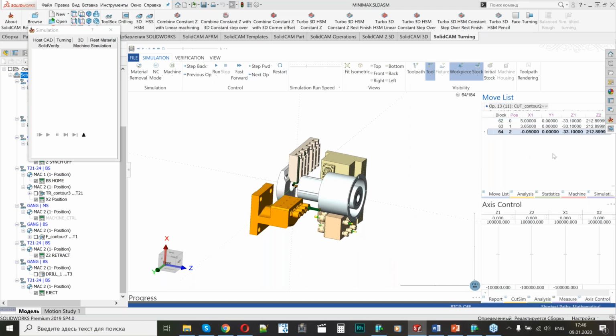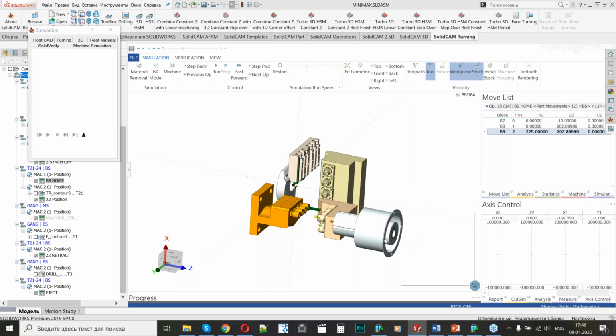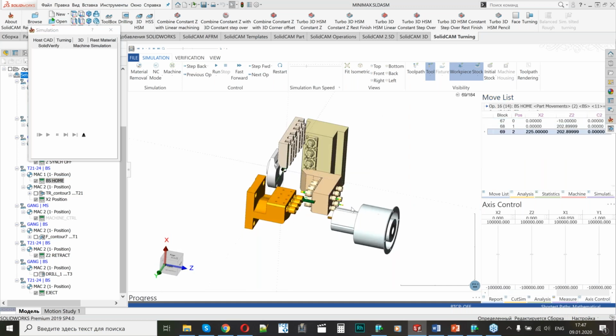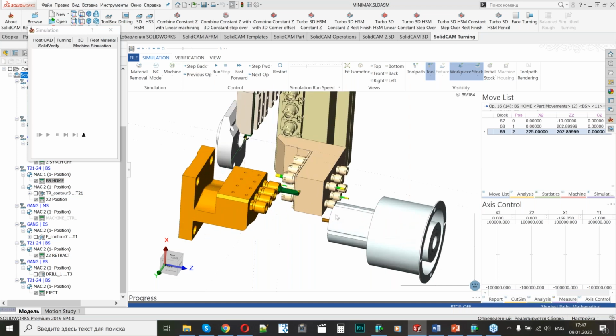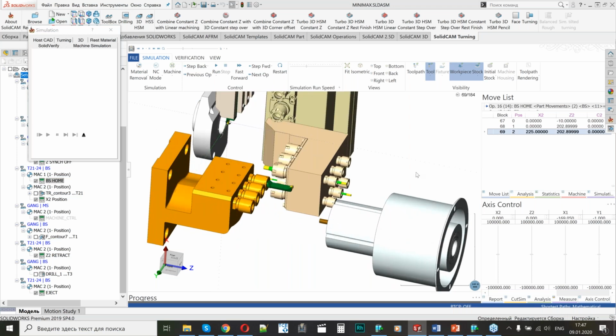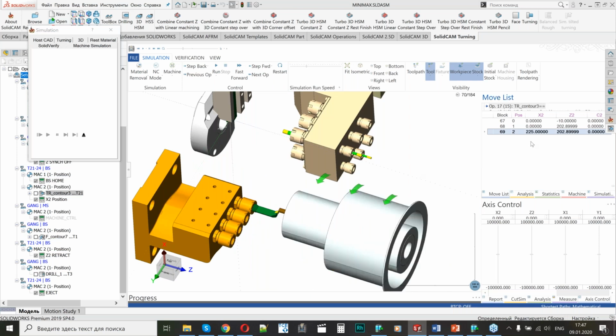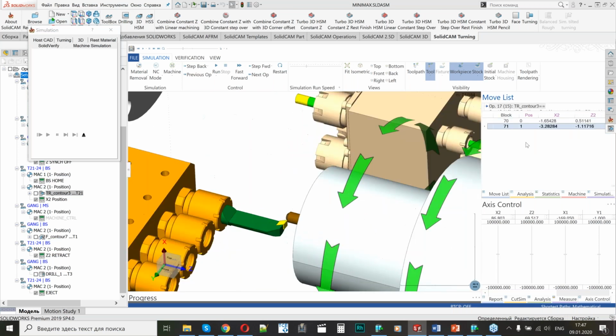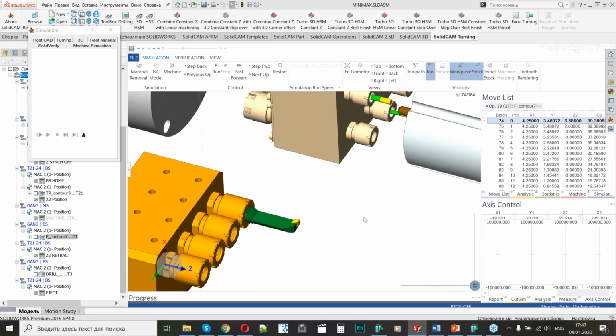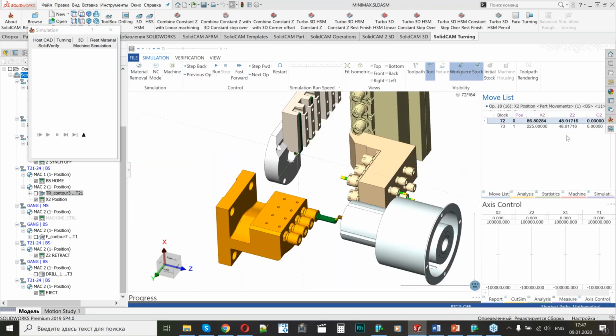And then I will have my cut-off operation and part transfer, and now my part is in the sub spindle, back spindle, and I can provide operations on the 2 tool blocks. The first one is for the turning, so I have a turning operation here, and then I will just go back. I have to move.